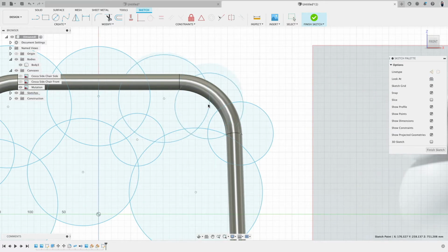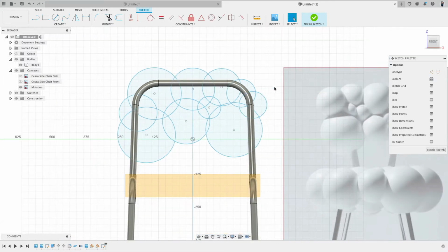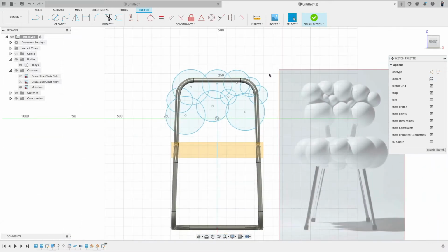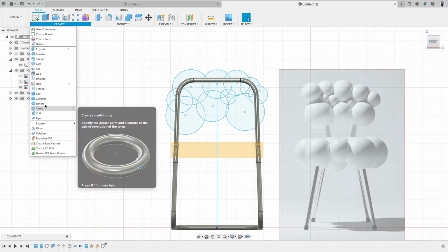You see, what did I do? Coincident constraint, delete it. We'll bring this one maybe to there and this a little bit to there. Okay, very good. Everything we have there right now is really more of a visual guide. Okay, good. Next step, finish sketch.